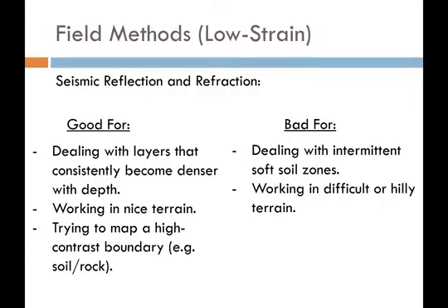They're great if you're dealing with nice terrain, and they're really effective. And in my own personal practice, they were always the most useful when I was just trying to map the boundary between two high contrast, high impedance soils, where the lower soil or rock was a lot more dense than the upper soil.